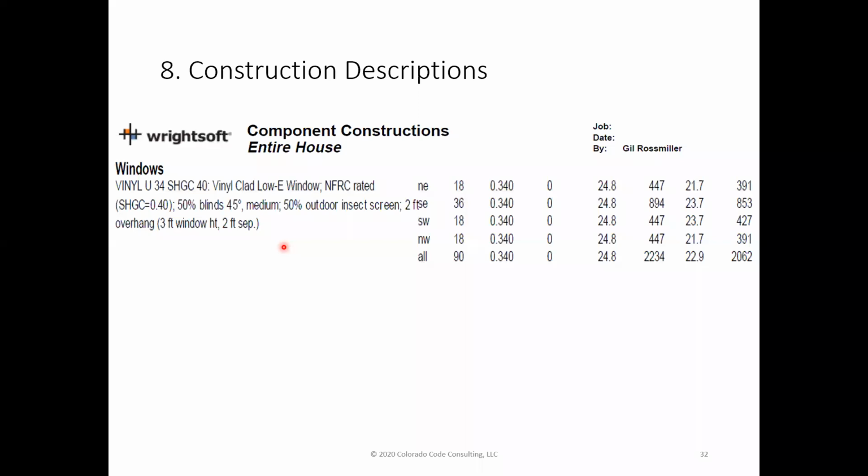This is a big deal because solar gains are the largest load for air conditioning. Solar gains meaning the sun shining through the windows, okay? It is a gigantic gain. It is by far the largest, well over 50% of the load, right? Many times it's over 50%.